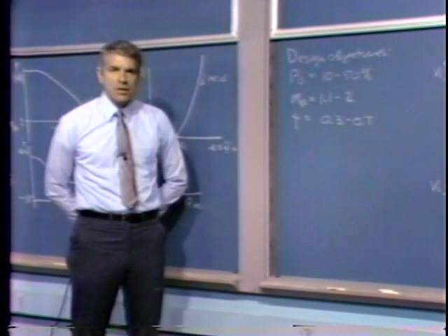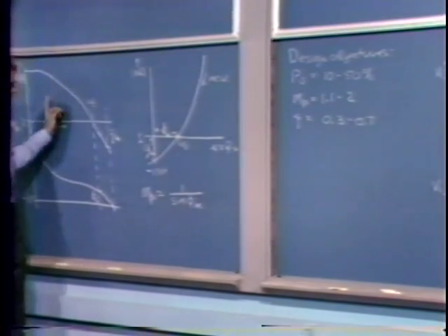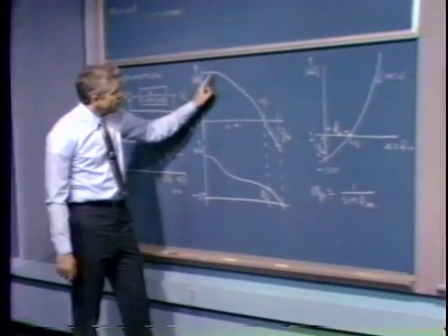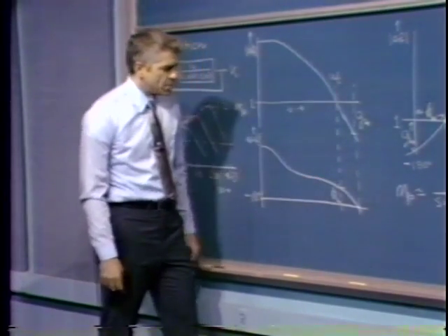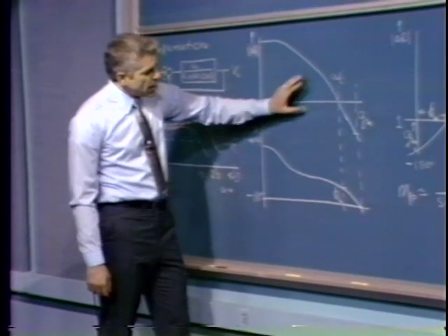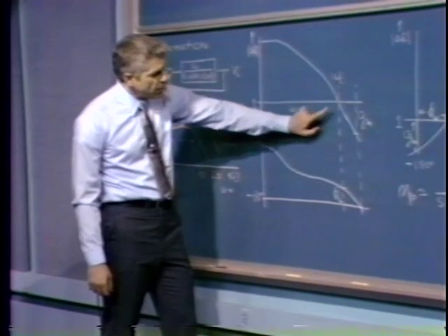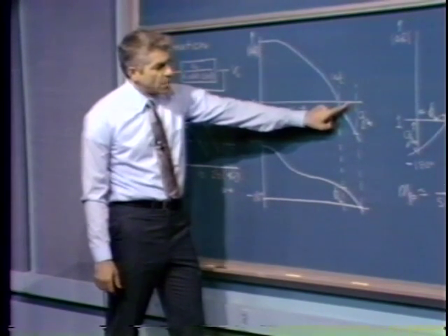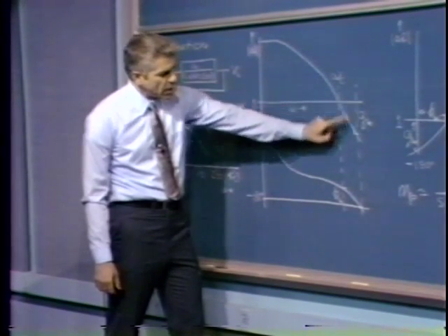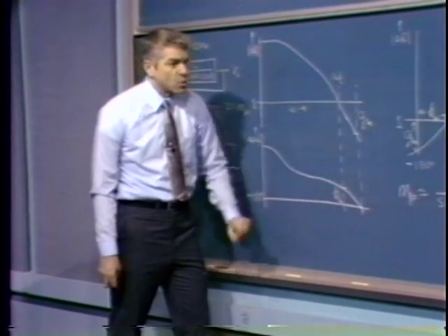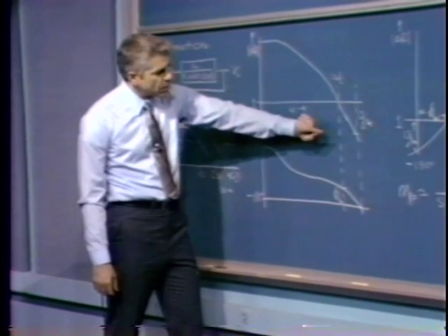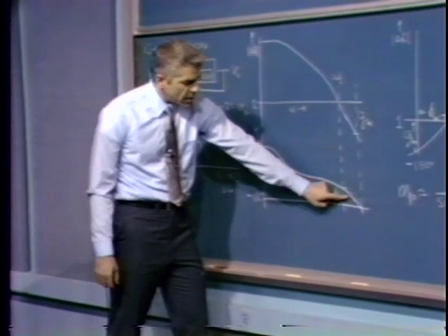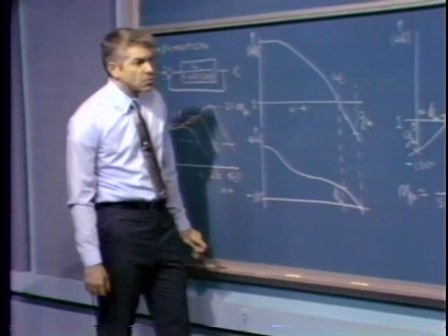But as general guidelines, we find, of course, that as we compromise stability, as we go to a relatively less stable system, the advantages we gain in exchange for that are generally a higher crossover frequency. If we have a typical AF plot like this, where the magnitude drops down monotonically, the angle again is, at least in the vicinity of the crossover frequency, a monotonic decreasing function. Now we find out that as we, for example, increase the AF product, crossover moves out, the system gets faster. Because we've increased the AF product, we get greater desensitivity, but unfortunately the price we pay is one of reduced phase margin, consequently reduced stability. So there's almost always that trade-off where higher values of crossover frequency and greater amounts of desensitivity invariably lead to smaller phase margins, consequently less relative stability.